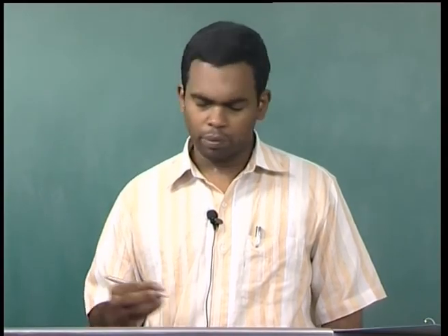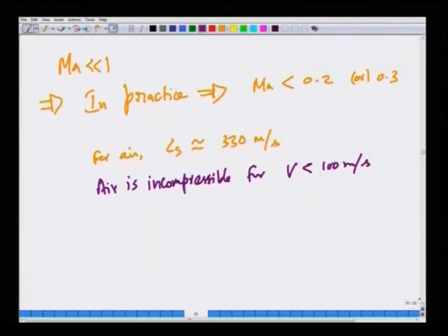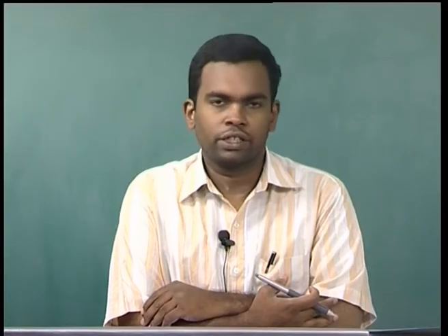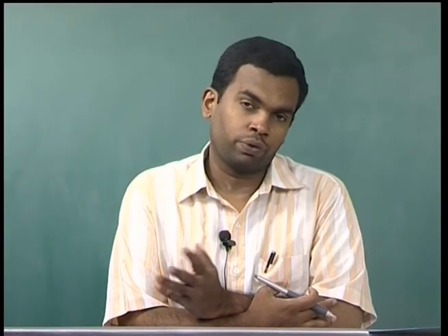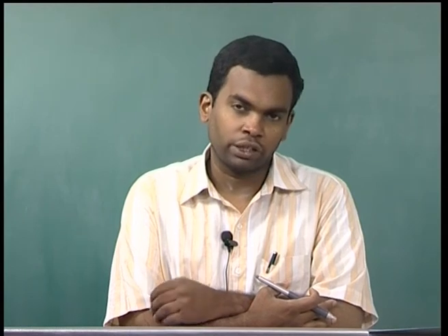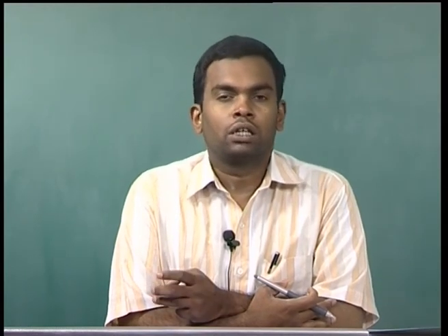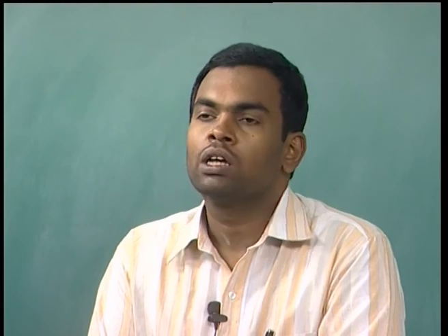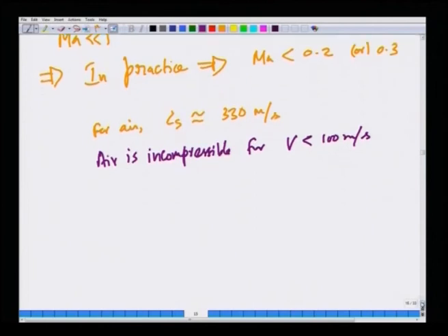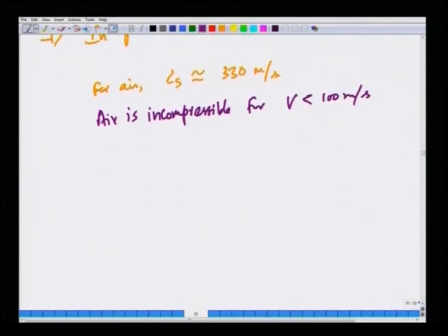But this is okay for many chemical engineering applications. We will not have cases where velocity is of the order of a few hundred meters per second in many chemical engineering applications. Therefore, we can treat a fluid such as air to be practically incompressible. Although air can be compressed, the density of air does not practically change much for the pressure changes associated with many chemical engineering applications. So, in this course we will largely deal only with incompressible fluids.